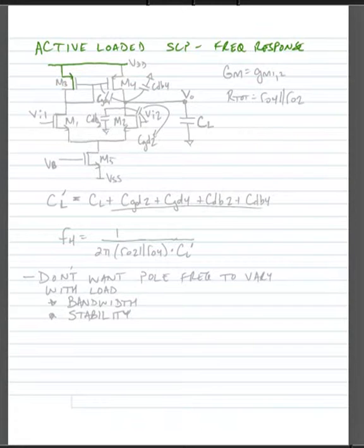So we're going to draw the NMOS input with a PMOS active load version that we've been looking at. Alright, our input transistors are our NMOS transistors M1 and M2. They're loaded by our active PMOS load M3 and M4. And finally, we have a tail current source M5 that's connected to a DC bias generator.